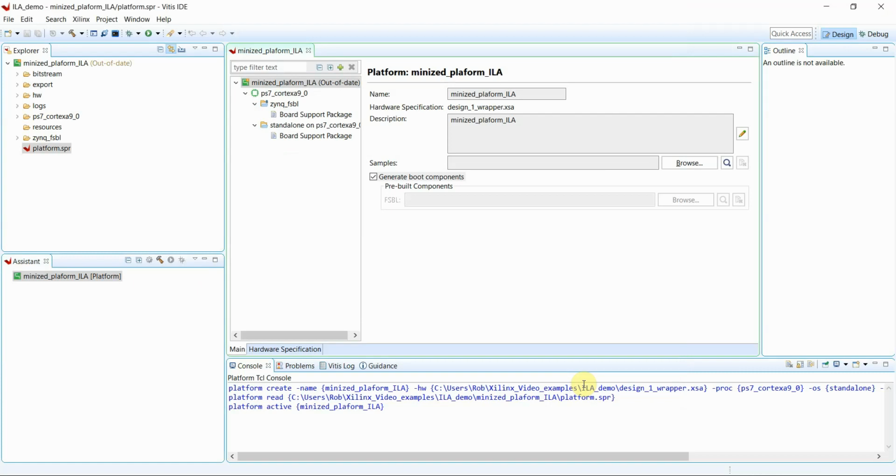All right. So one of the things that the Vitis tool allows you to do is develop firmware from a higher level. And what I mean by that is if you want to use the UART, for example, you don't have to know what the register address is for setting the baud rate, or what the register address is for loading the transmit register. You can use things like standard I/O and just do a print to the standard I/O device. Now by default, the tool wants UART 0 to be standard I/O.